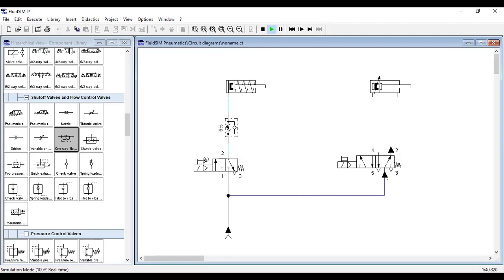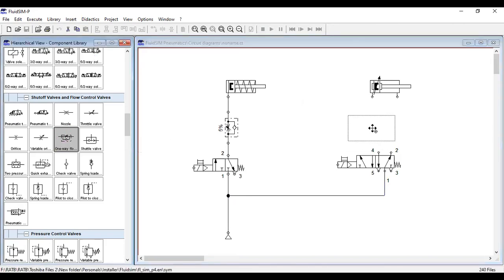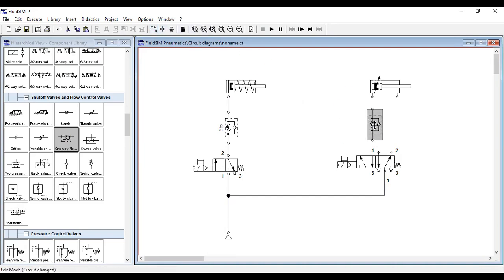As you can see in the single acting cylinder, to control the speed would be difficult, because the one that enables the cylinder to retract is the spring. But unlike with the double acting cylinder, as you can see, you create two flow control valves.